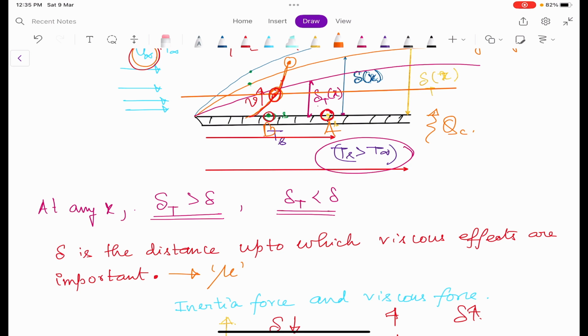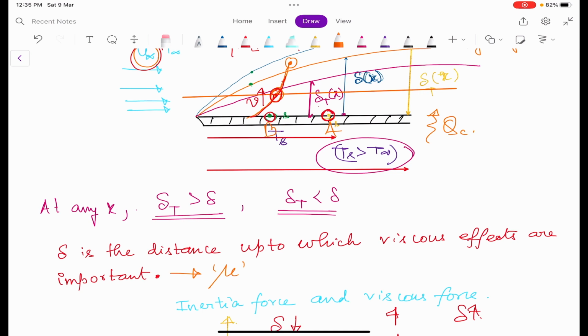Now if the thermal conductivity is more, then more and more heat can be propagated, and at a particular y the temperature will be greater, because the work of the plate is to heat the fluid. So if the heat conduction is very good because the fluid has a very good thermal conductivity, then at a particular y the fluid will have a greater temperature.